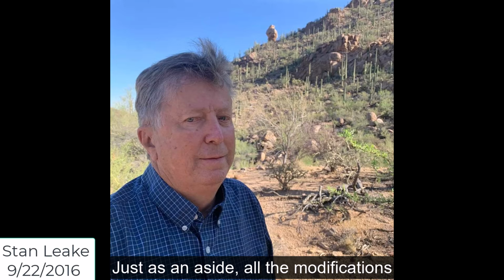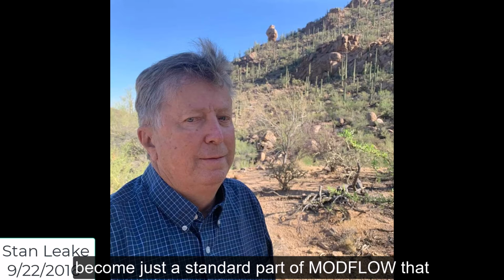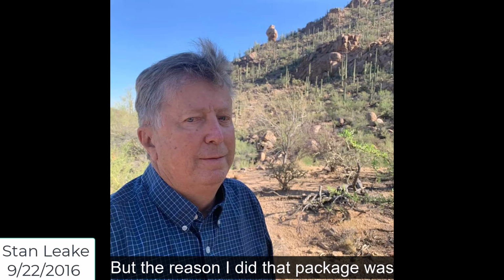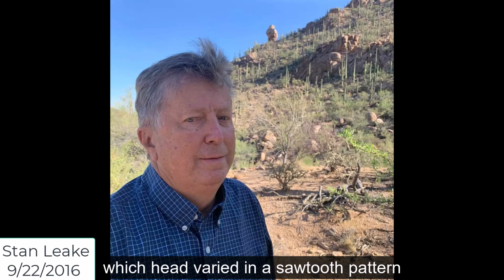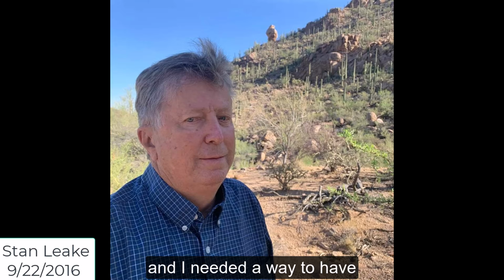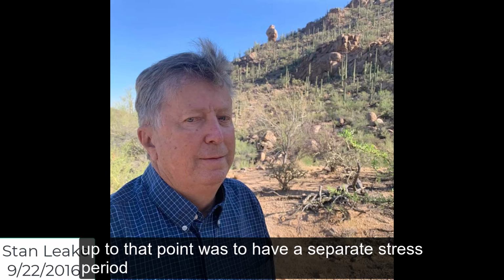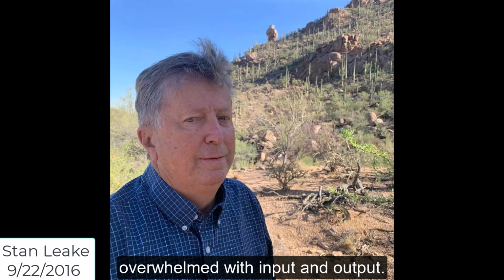And just as an aside, of all the modifications I've done for MODFLOW, the one that is most widely used is called the Time-Variant Specified-Head Package, or CHD, and that's become just a standard part of MODFLOW that anytime there's an update, it's always put in the new version. But the reason I did that package was when I was testing the subsidence package, I had something called a ramp load test problem, which varied in a sawtooth pattern, and I needed a way to have this boundary condition go up and down. And the one way it could be done in MODFLOW up to that point was to have a separate stress period for every little step change in head, and I needed those step changes to be done more automatically so you wouldn't be overwhelmed with input and output. So that original version of the Time-Variant Specified-Head Package is documented as an appendix to the Interbed Storage Package.